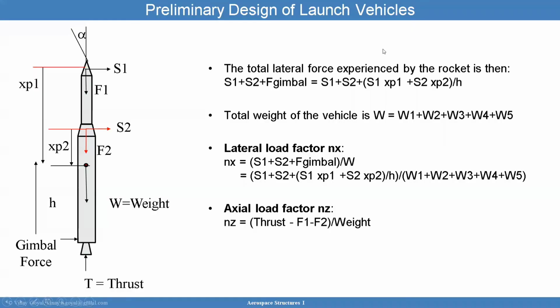So if I have summation of forces equals MA, for example, and I divide both sides of the equation by the weight, on the left hand side you get this exact same equation. On the right hand side I get acceleration divided by g. That's telling me how many accelerations I have above g. That's what this lateral load factor is.